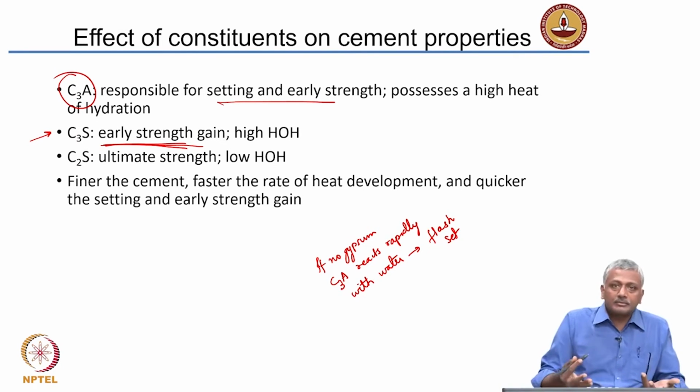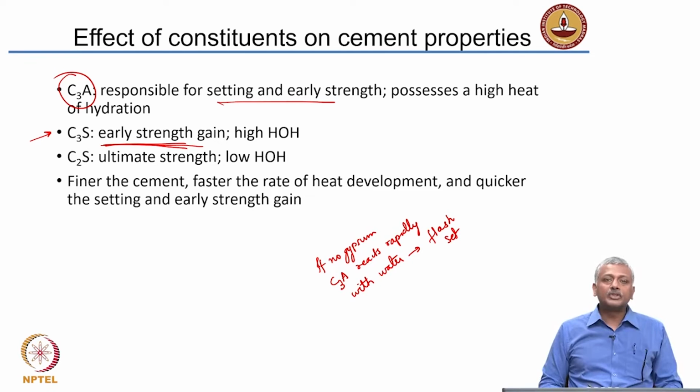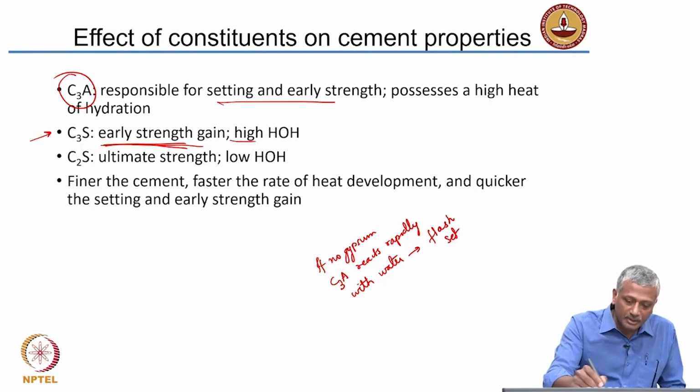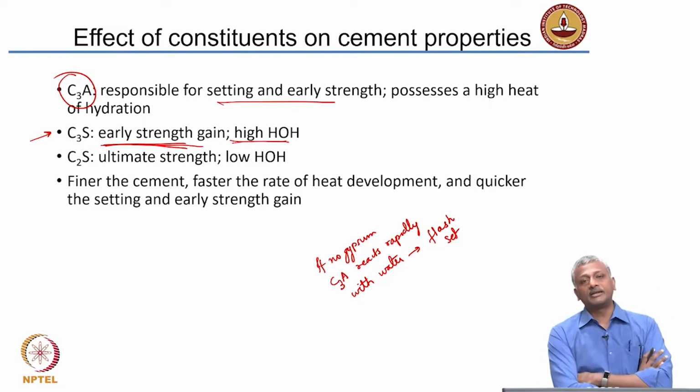And of course, it does not come without any price. You have to pay a price for it. It possesses a high heat of hydration. That means it evolves heat rapidly and the potential for cracking could be significant.